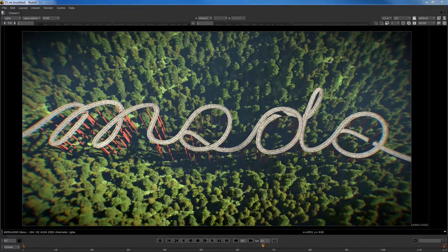Let's just scroll down a little bit. Can you change the distribution based on height? Yes, you can. If you use the texture-based surface generator, you can influence it by textures, and if you just map a gradient on the y-axis, that will give you effectively the height of the terrain, and then you can use that to influence the density of the particles, and that will work quite nicely.